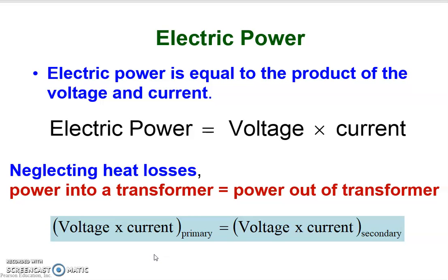Which means that how much energy or power will be lost is determined by how big the current is. So our purpose is to lower the current when we transmit the electricity to your home device. We know that the bigger the current, the smaller the voltage. But now we try to lower the current, which means you have to increase the voltage as high as you can. So that's the reason we need a transformer to transmit the energy.